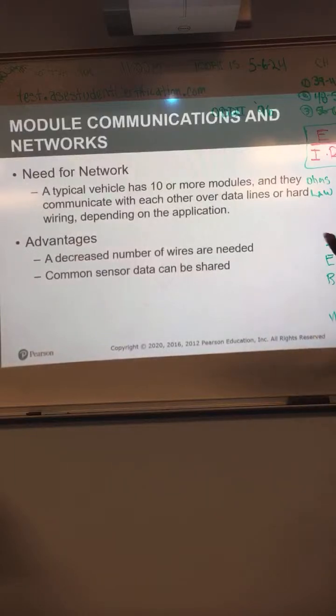But now they just give you a pass-fail, which doesn't really help you when you go to repair it. So you would have to take it somewhere that's authorized to do a repair. They'll put the machine in analyzer mode, and that will give them the actual readings of what's going on, and then they can tell you why the car failed. But if it's 96 or newer, it's tested through the diagnostic connector, not through the tailpipe, okay?